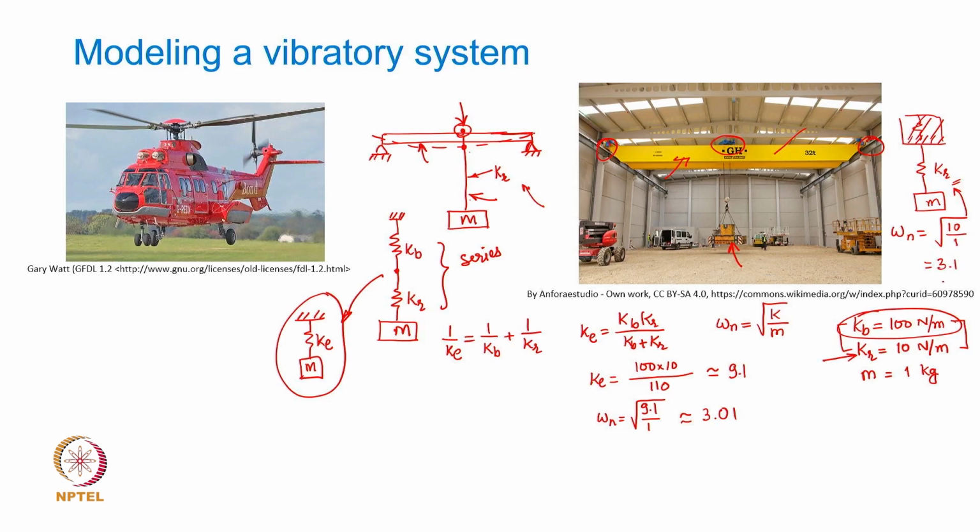So, what basically we are saying is that the natural frequency that you obtain by simplifying the model, particularly when there is such a large difference in the values of the two springs, is justified, and the amount of error that you will get, this also is in radians per second, I am sorry, you can see that 3.1 and 3.0 something would be like hardly any difference in the values estimated.